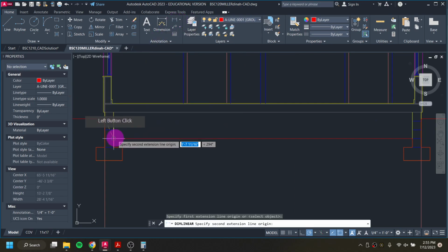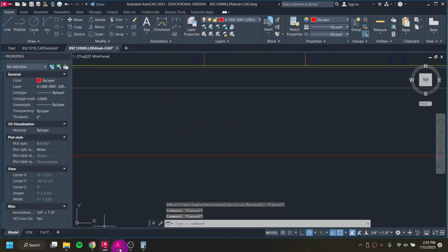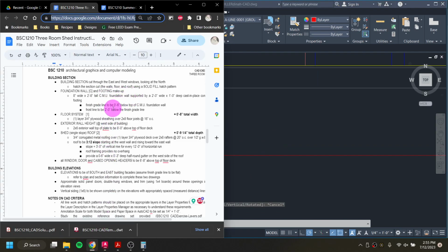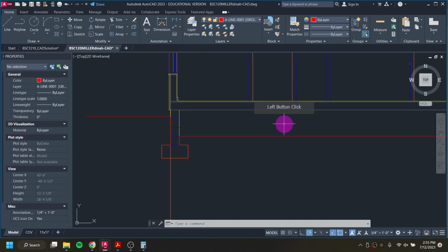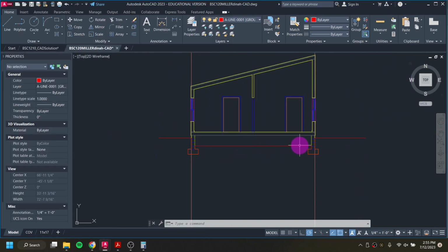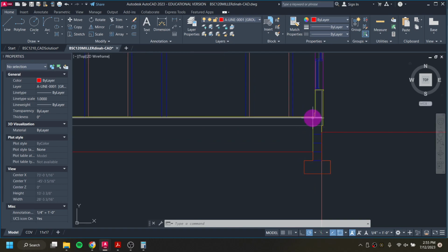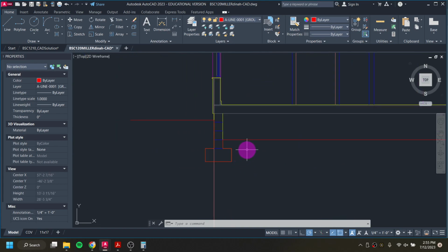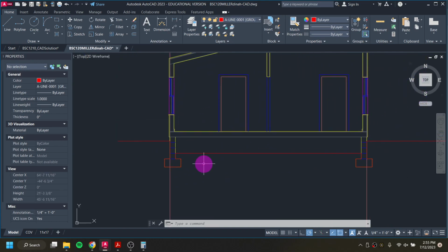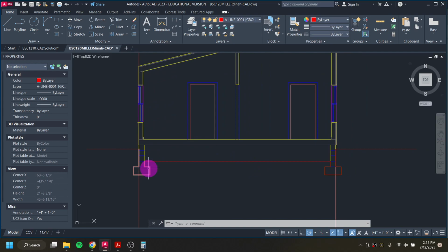How much then is that from the frost line? 1 foot 6. So I'm just going to boop, boop, boop. Frost line is 1 foot 6. Whoops. There we go. It's almost like it never was there. Because I think I was doing 2 foot when I did the first drawing. I did 2 foot from the top of the floor to where that frost line sat, is where I was measuring off of, not the finished grade. Okay, that just looks better, and it would make more sense to have the footing that deep anyhow.